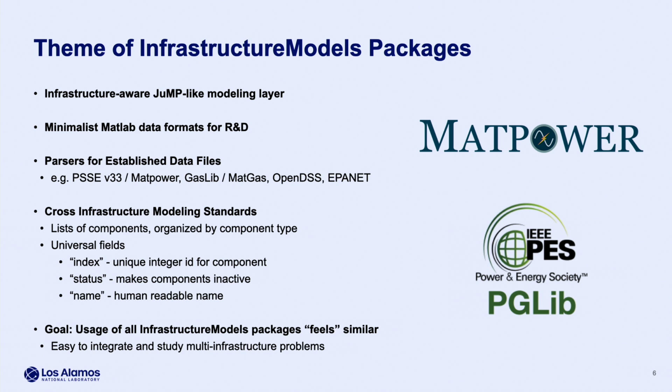Then we have a minimalist data format. You may be familiar, when you load a power network data set, it comes in either a MATLAB, like MATPOWER format, or PSS/E. If you're doing distribution modeling, you've got GridLAB-D, OpenDSS, CIM. There's all these formats. Most of the industry formats are really difficult to use. I don't know if you've ever tried to parse one of those. It's really crazy. But one of the successes that MATPOWER had was that they defined a network data format that was really easy to use. You can just look at it in a table form and understand what's going on.